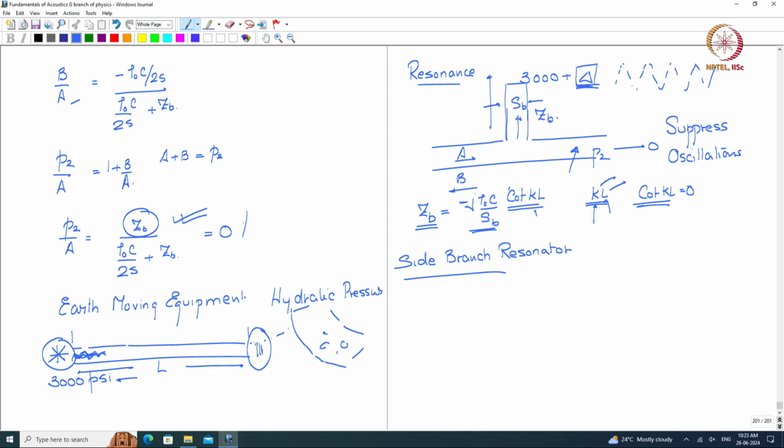As a result, its impedance drops, so that the input pressure dominantly interacts with it and the pulsations downstream are 0. So this impedance is higher, so the input pressure interacts with the low impedance side and this side is left alone and the pressure pulsations are 0. So these are very good solutions for this kind of a problem.